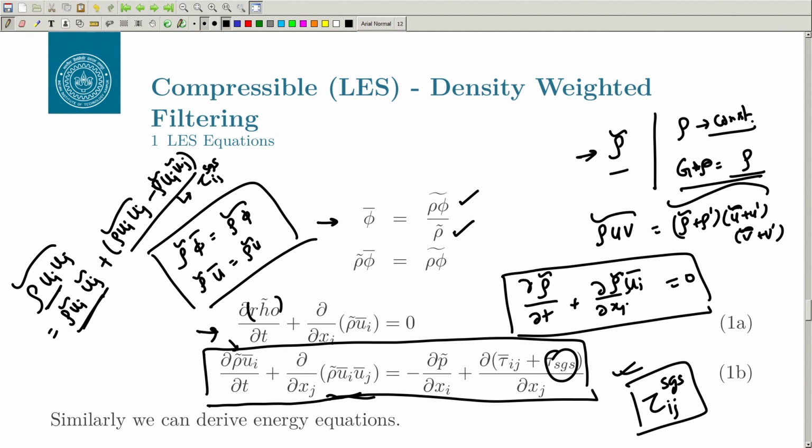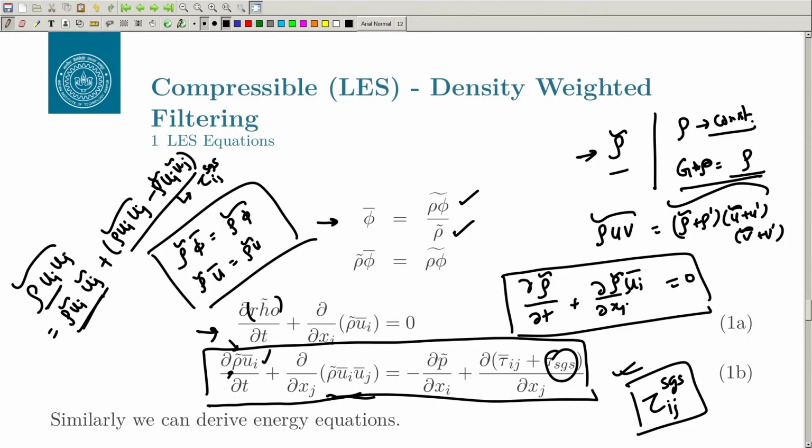So, essentially you have the Navier-Stokes equations, you are solving for the variables which you can call resolved variables, u, v, w, p, rho and so on, and you also add a subgrid stress tensor, where the grid size is sufficiently small. So, that is what you are going to do. That is why this ui bar and rho tilde are not the average equations, either Favre or Reynolds; these are filtered quantities, it can be implicitly filtered or explicitly filtered.